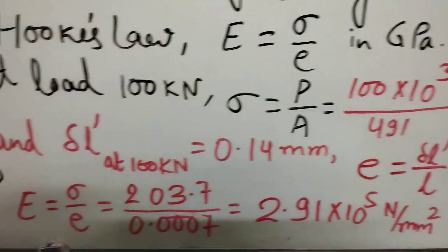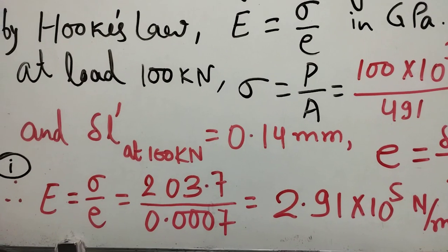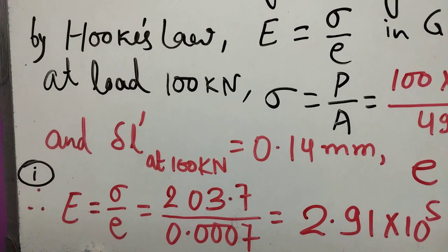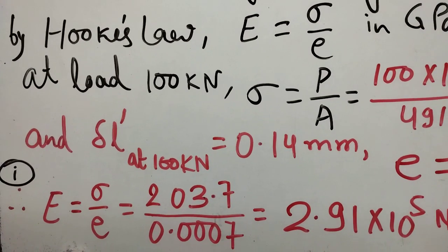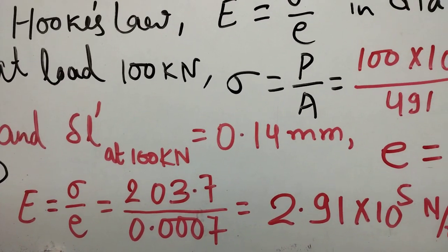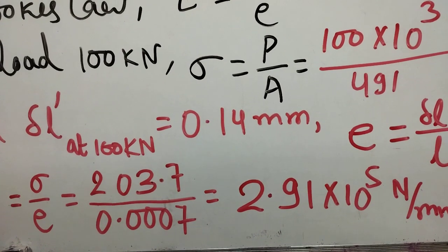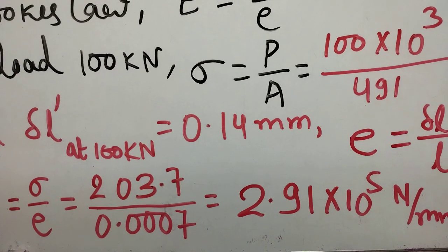We put here the stress and strain values, and we find the Young's modulus E, which is 203.7 divided by 0.0007 Newton per millimeter square.